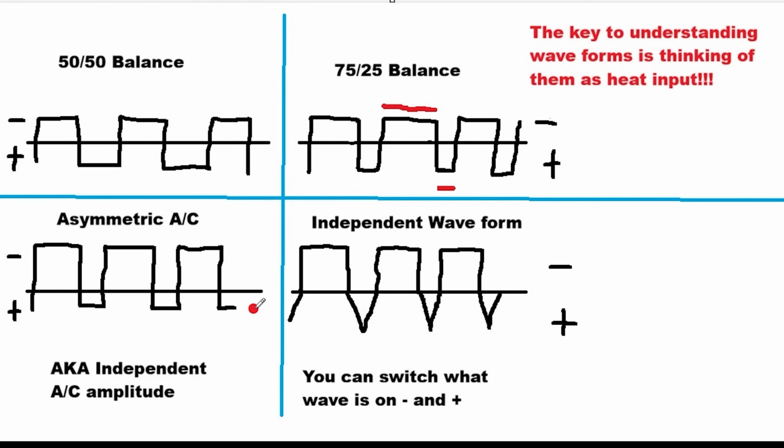Well, the truth is you got to remember that when you TIG weld on aluminum with AC, the whole purpose of the cleaning action is just to get you a clean puddle, to strip that surface oxide off. Well, once that surface oxide is stripped and the argon shielding is over that molten aluminum, you no longer have any kind of oxides forming due to reaction with oxygen. Therefore, you can get away with reducing your heat input via changing the wave on the positive or the amperage, and you'll still have a clean enough puddle to work with, but you can again put all of that heat input directly on the negative to get the most amount of penetration that is possible.